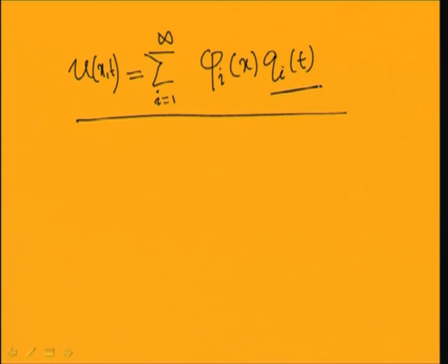So, the resulting free vibration is the summation of all the modal vibrations or modal mode shapes, all the different mode shapes and time modulations. But when you know that the system is excited at a particular frequency, then we may truncate this equation, and instead of infinity we can truncate it to a finite number of modes. In that case we may take say 2 or 3, or depending on the problem we may take n.